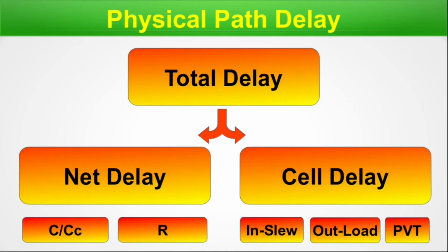So these are different track and height. Even for a single cell, all the delay values will be different for different tracks, and these cells are also packaged in different files. So all possible permutations and combinations of the cell height, process, temperature, and operating voltage, etc. give birth to a huge amount of data, which is captured into the .lib file for any standard cell library. So guys, I think we have talked enough on this slide.